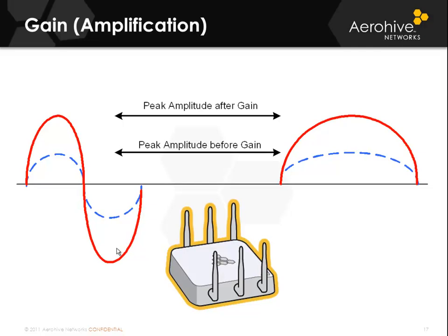Active gain is caused by the addition of an amplifier onto the wire that connects the transceiver or the radio to the antenna. The amplifier is usually bidirectional, meaning that it increases the AC voltage for both inbound and outbound traffic. Active gain devices require the use of an external power source, whereas antennae are passive and do not require such a power addition.